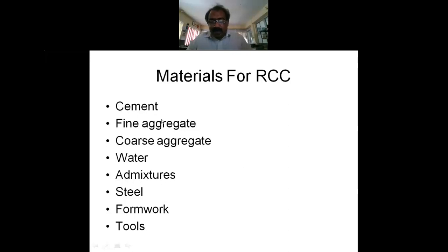Whatever good cement, good concrete, steel you may use, if the water is salty, objectionable water, then everything may get deteriorated. For funny things about our engineers, I am very strongly saying, there was an argument between me and a site engineer. Sir, how can we expect good water? Whenever I go to site for checking the concrete, without hesitation, I take the drum in which we are putting water. I take the water in my hand and then taste it. Somebody may hesitate, but I don't hesitate. Yes, that is our job. If I am not able to consume the water, if I don't like the water, I don't allow it for the concrete.